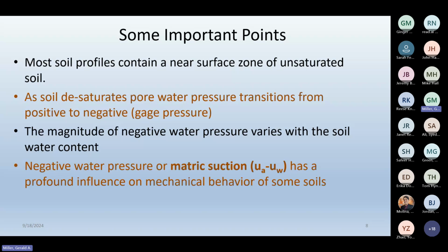In many soils, the pore air pressure is zero. It's at atmospheric pressure, that's zero gauge pressure. That means the suction is essentially a measure of negative water pressure. That's particularly true in sandy soils. And it has a profound influence on the mechanical behavior. And you're going to see that through some of the data that I present today.